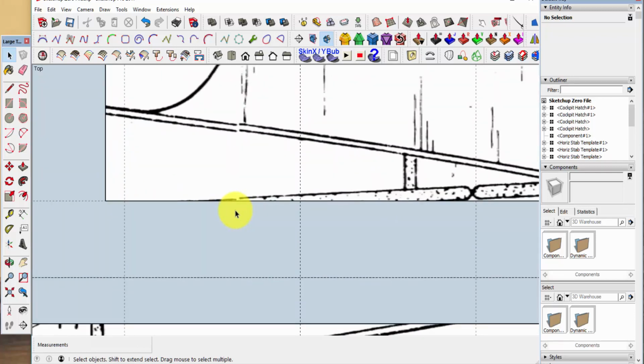So I'll come in here one more time, and our tape tool will go up 3 millimeters from our original baseline. Move it. Let me get on the green axis. Hold on just a second. We've got to make sure that we're traveling on the correct axes. Now we'll go up 3, put that there. Now we'll come here, we'll come down 3, and put that there.